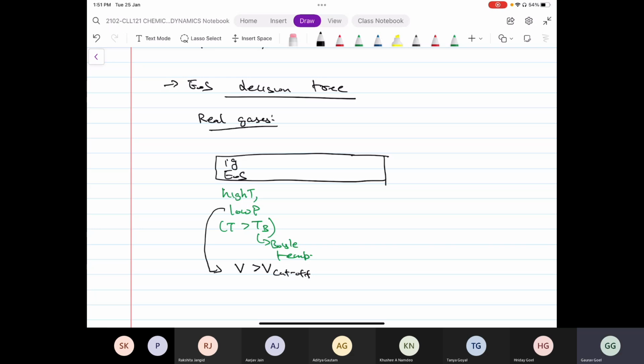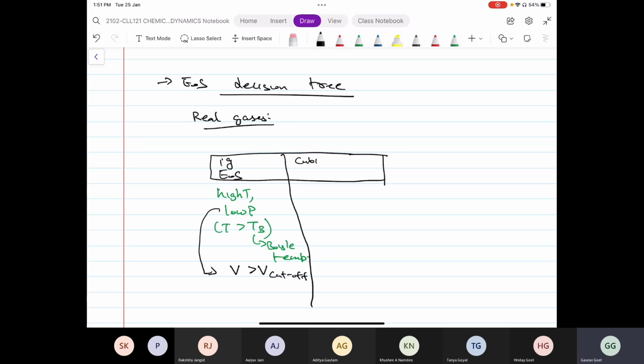There are rules of thumb available in terms of the density at which you can use the ideal gas equation of state. And of course, if you want to be very sure, then you use some other more accurate equation of state at the given conditions and check whether the ideal gas estimate was correct or not, just the way we did right now. Okay. Next is your cubic equations of state.